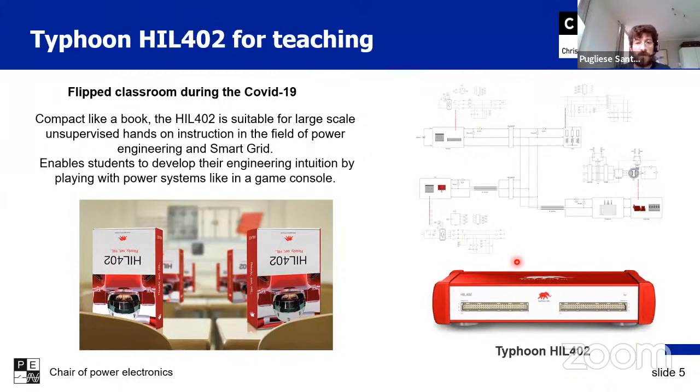So you can control it online remotely from home. You can program your DSP with all the control features. This DSP will interact, giving a PWM signal and measuring the current and voltage from the I/O, and your controller will behave like it's connected to a real motor.